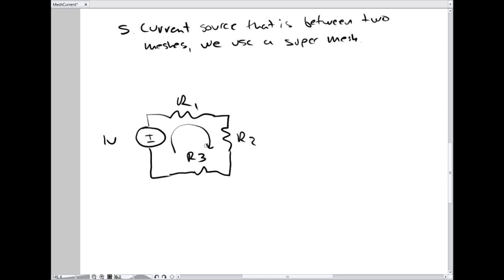Then I consider a positive voltage, voltages where if I were to have a resistor there, the voltage would follow the voltage drop. So according to passive conventions, I don't have to do a sign switch in Ohm's law. So for all my resistors, I say a positive voltage is such that that voltage follows the voltage drop.